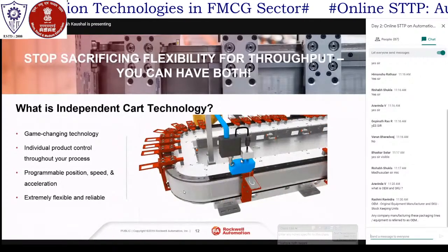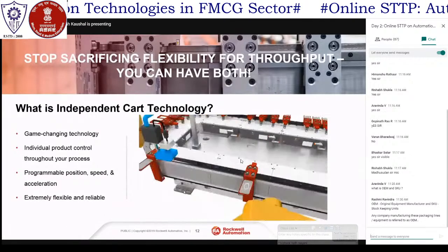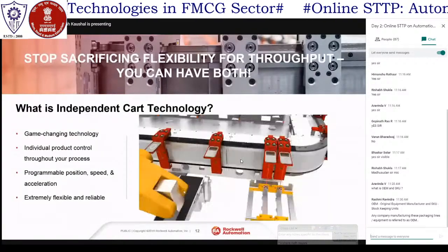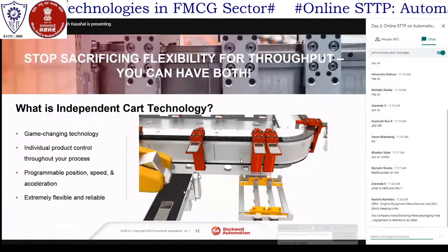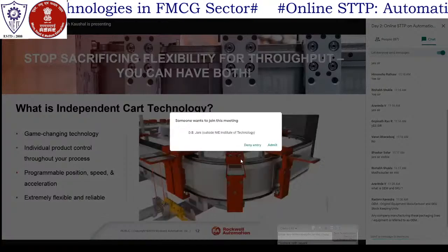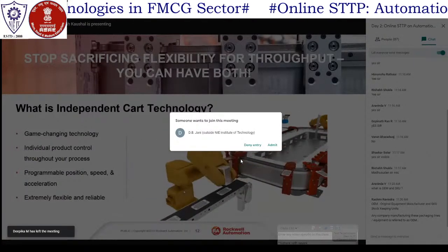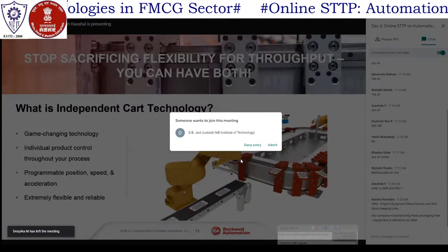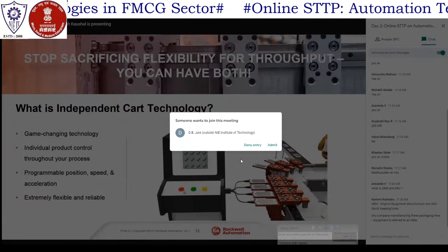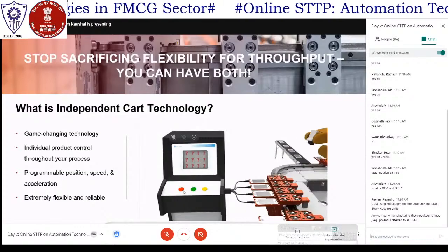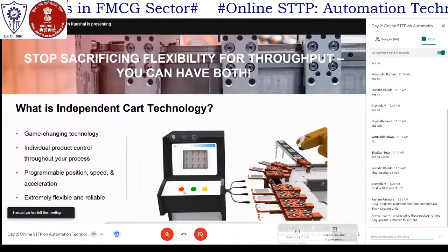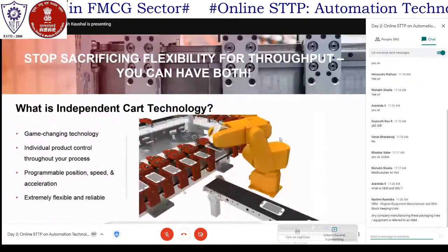So depending upon how much speed or time is required for a particular operation, you see that you're either using a single station or you're using multiple stations to perform the operation at the same time. And you are also able to combine the continuous flow of the products as well as starting and stoppages depending upon the requirements. For example, testing is a long time-taking activity. That is where you see that there are multiple parallel stations which are performing a detailed testing on the solution, right?